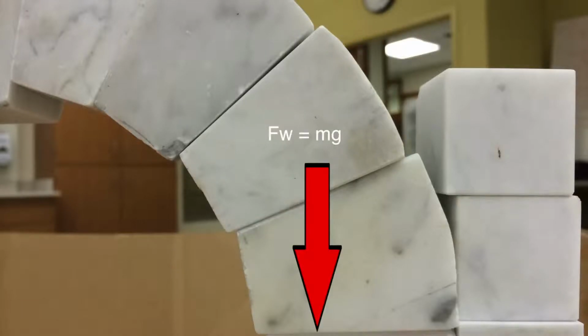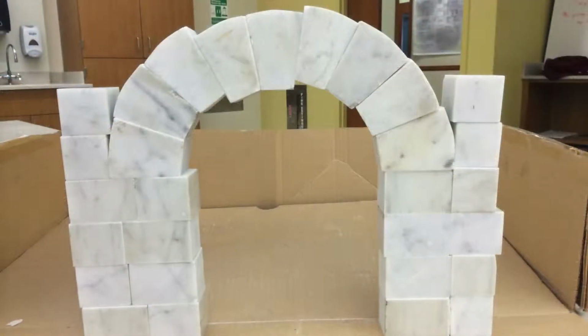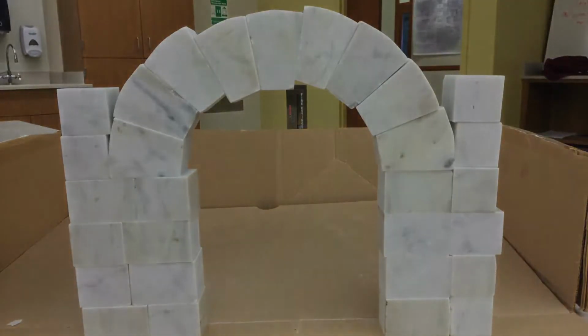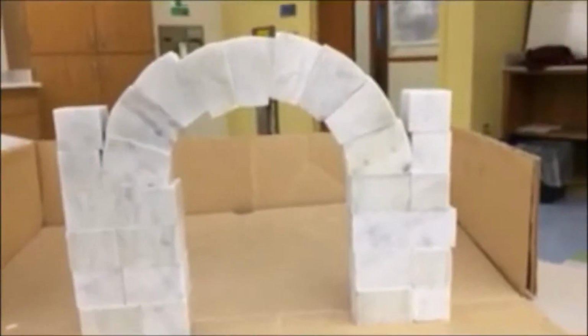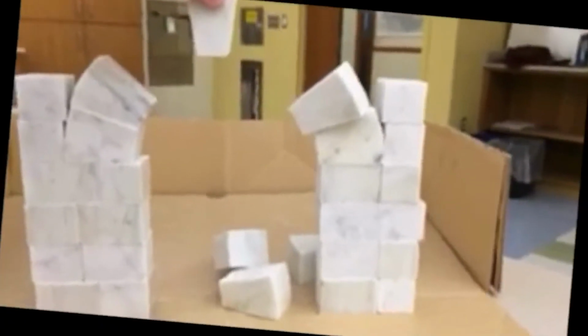If this arch, which has substantial mass, can remain erect without any cementing, imagine how strong an arch is with strong, resilient cement. This makes arches suitable structures to use in bridge design because of how durable they are, and the manner in which the forces are distributed throughout the structure. The arch in the demonstration was at equilibrium because no part of it was moving, but when external forces are added to an arch, its equilibrium position shifts. As long as no voussoirs can move outward, then there is no room for other parts of an arch to fall, and it will remain intact.